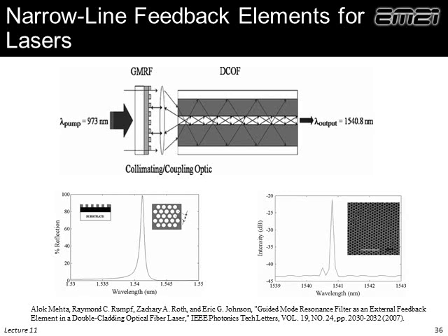And we talked about this application before, wavelength selective mirrors for locking lasers. Lasers have a resonant cavity where there's photons bouncing back and forth. And the mirrors at either end, if we could make them be filters, then we could laze over a narrower line width. So guided mode resonance filters, we can make them arbitrarily narrow. They're excellent, excellent choices for locking lasers.